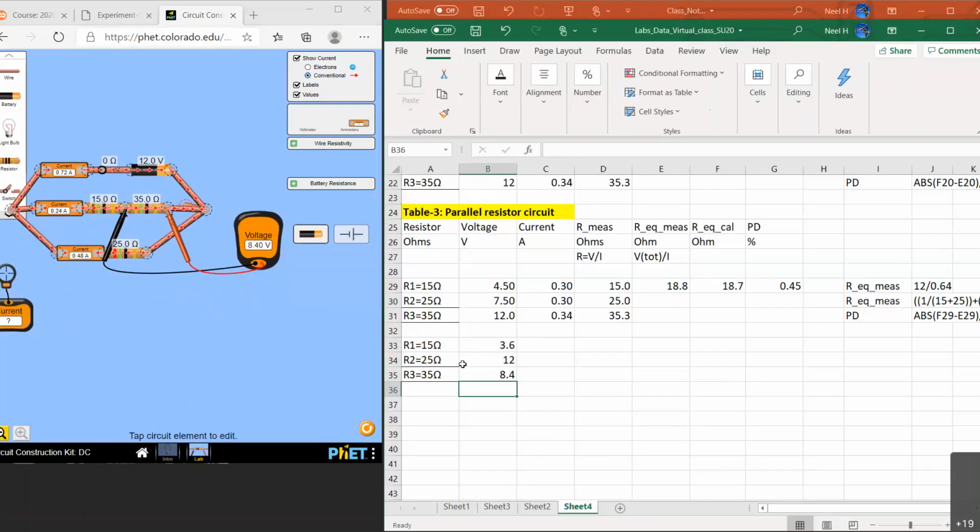Remember that if you're working on the second case, R1 and R3 are serial now, okay? So you can write that information here, R1 plus R3 directly, and then parallel with R2. So that's case number 2. That's important because the way you calculate later will change everything.